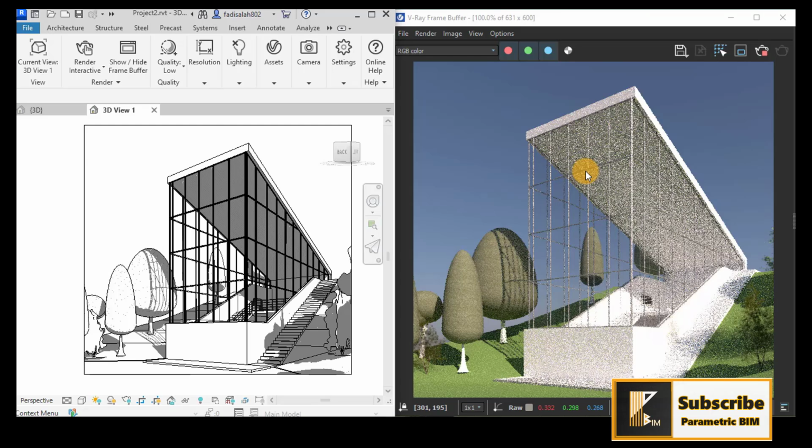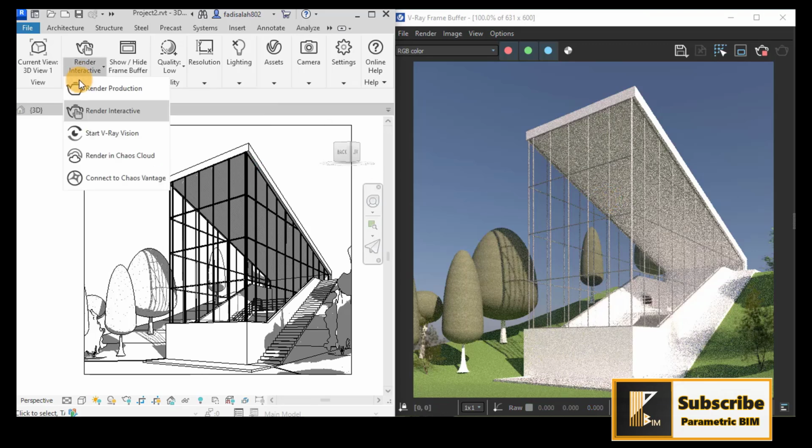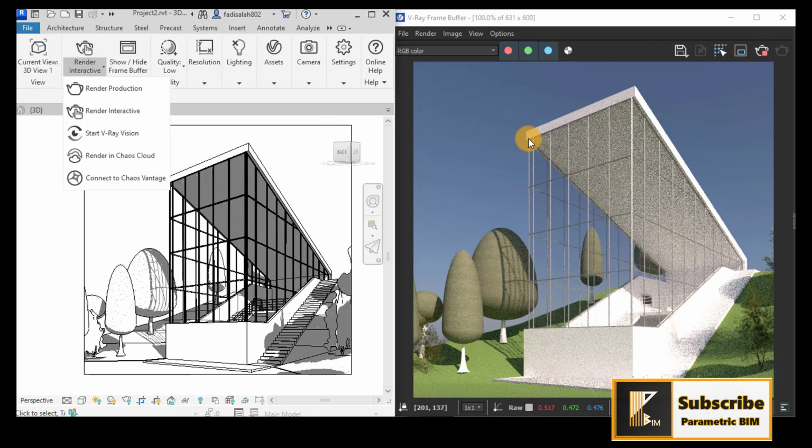So this way we have a render working here in low quality mode, and we can now change anything in the material or lighting and re-render using the render interactive. It will save the settings and apply the changes. But we also have here the start V-Ray Vision. The start V-Ray Vision is a real-time render, which means that we can change things in Revit and the changes will be reflected on the render. So let's see how it works.